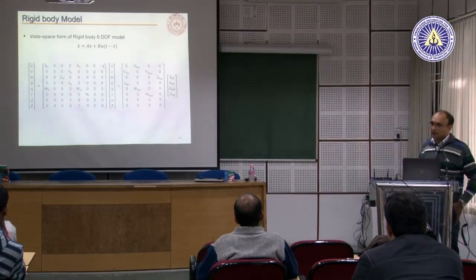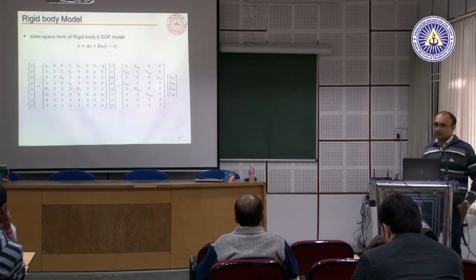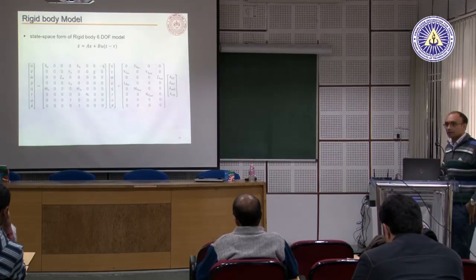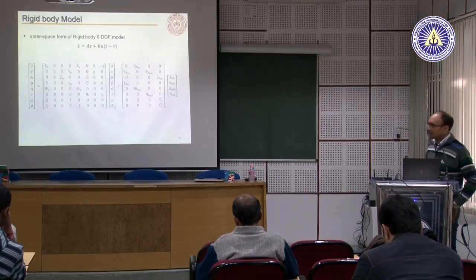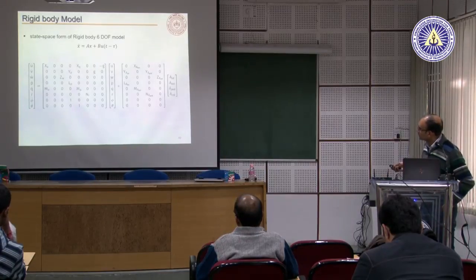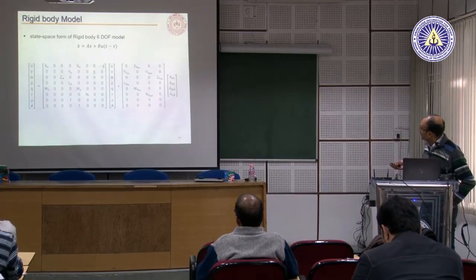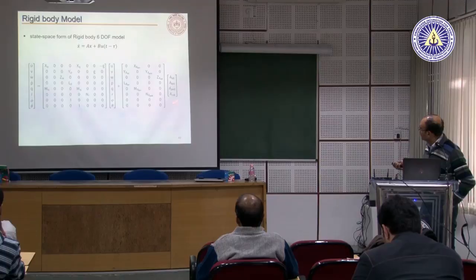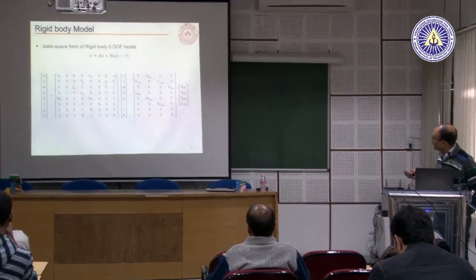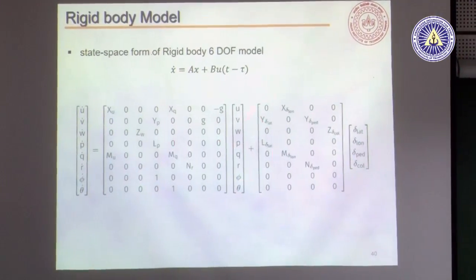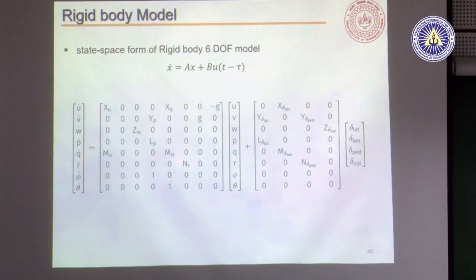So we left that out because it's anyway simplified dynamics. Just the yaw alone is very simple. It's not very difficult to design a controller just to take care of yaw dynamics separately. So that equation in psi is dropped. The corresponding inputs are your lateral, longitudinal, pedal and collective. And the equation will be populated in some form like this. Now we have to give guess values for all these things. And that is where the challenge comes when we try to identify the model using CIFER.